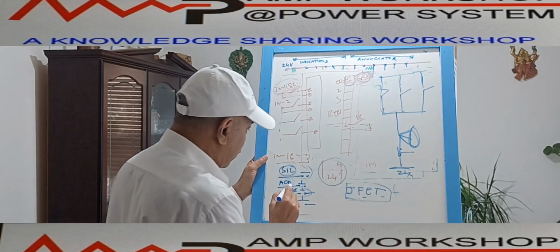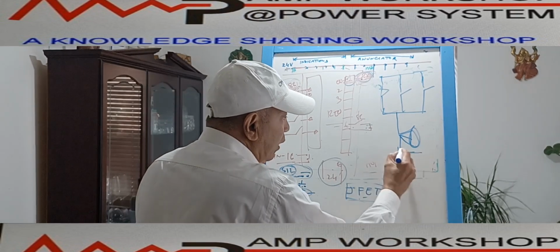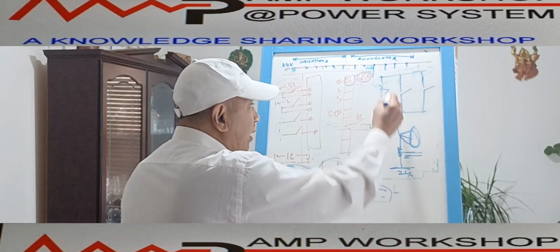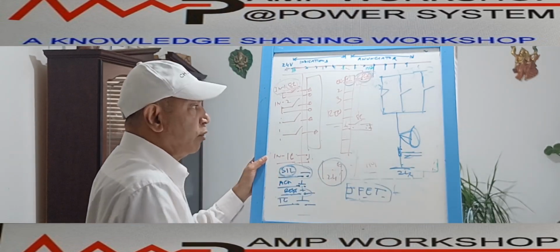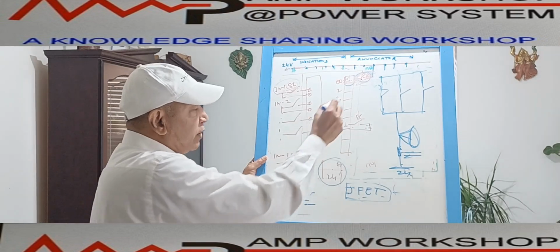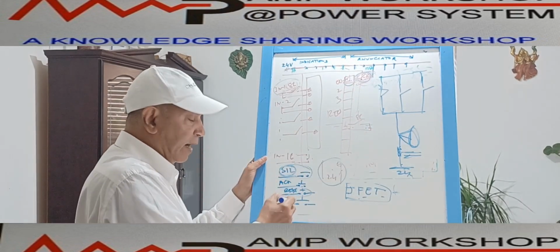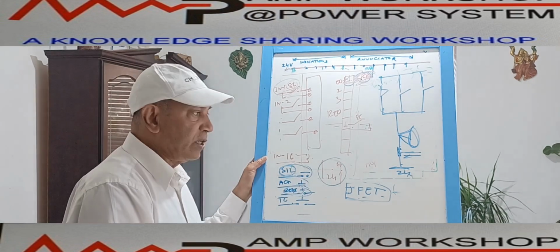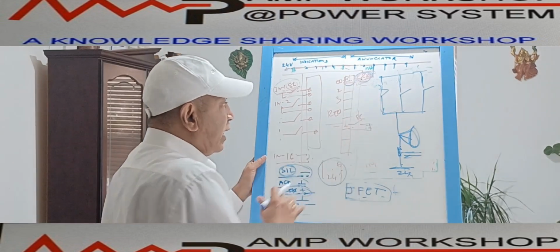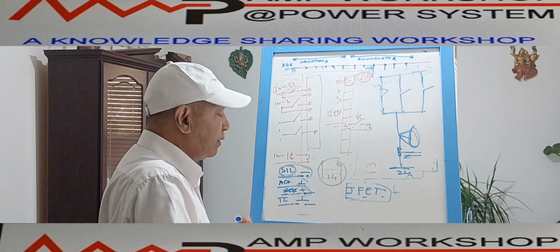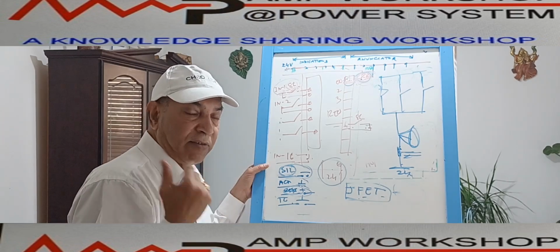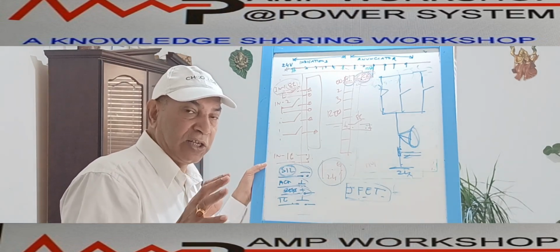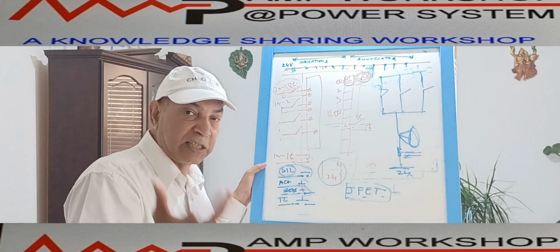This push button which we call silence is electrically connected inside the PCB like this. The moment you press it, the horn circuit is disconnected immediately, and so the sound goes off. And the reset push button: we have shown the indication lamp connected in parallel with this, and that gives your reset push button. And the test push button we have already discussed. So the present-day annunciator is like this. Now, in addition to this, we said the most advanced annunciator has a lamp that is not steady but in flashing mode, and the flashing is also of two types: a fast flash and a slow flash.